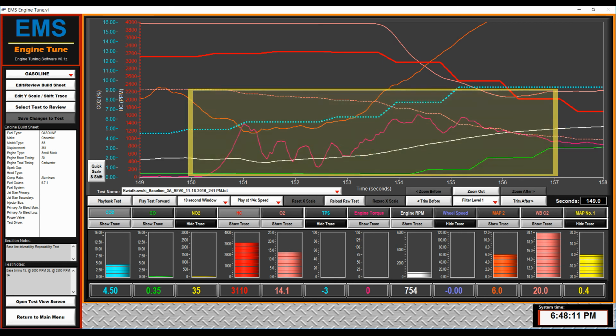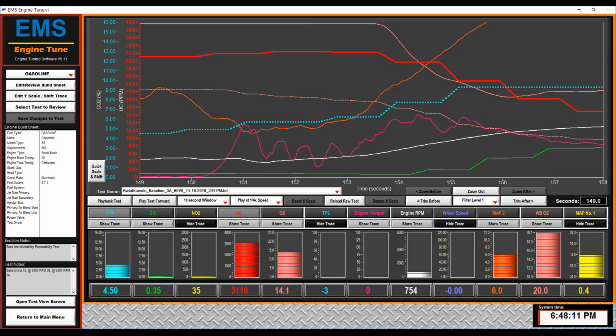Since the torque that we are measuring seems to be on average what it takes to launch the Nova, we know that if we have torque at 30 to 40 pounds, we will have more than enough to drive the vehicle. We also know that the CO should be at about 2 to 3%. This will give us a target on the bleed, or changes in the air bleeds within the system,